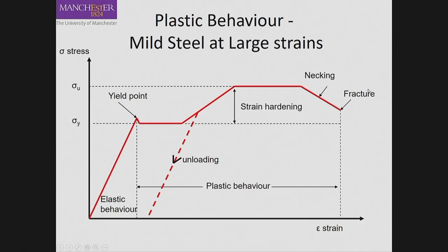Okay, so necking, we said that it happens because the cross section reduces at a certain stage, and that's why the stress starts to fall. But actually the load doesn't fall. The stress does, because we divide the load by the original cross section. Now if we did take into account the reduced cross section, the stress would increase until failure, as did the load in the previous case.